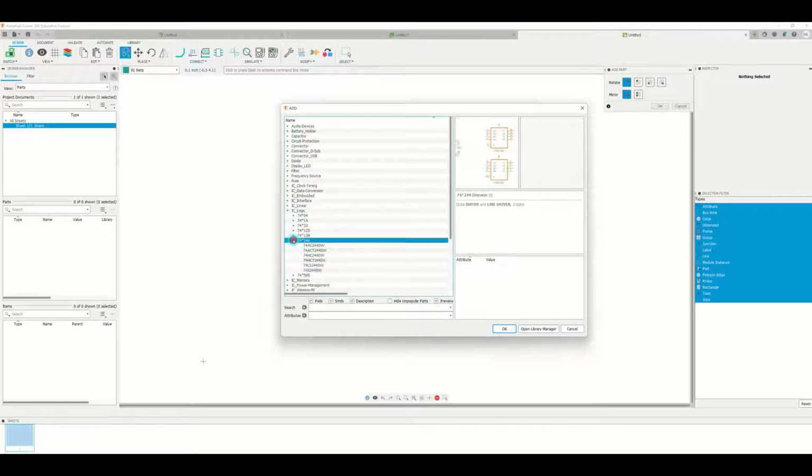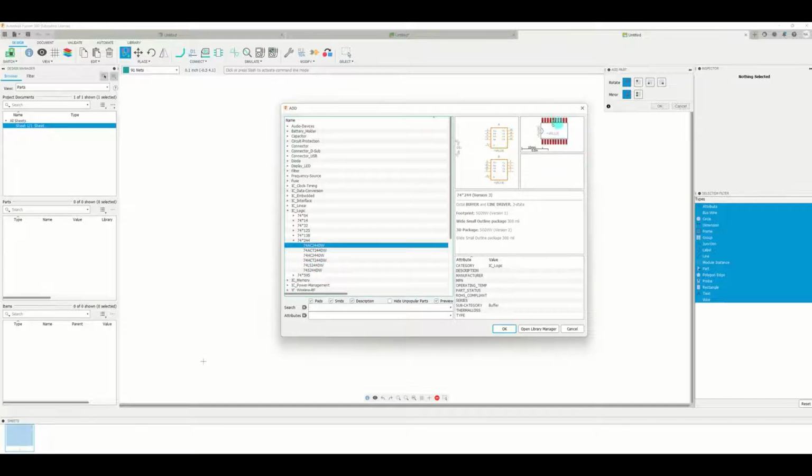So open the 244, and we select the different types of 244. You would see on the right the component, and later on here you would see the actual device. If you select, for example, this one, that will be the footprint of that component, and that will be what will be displayed. Now what we want is DIP. If there is a DIP package, we'll see, and click the other ones. Okay, so there's none, meaning we have to later download or connect to the library.